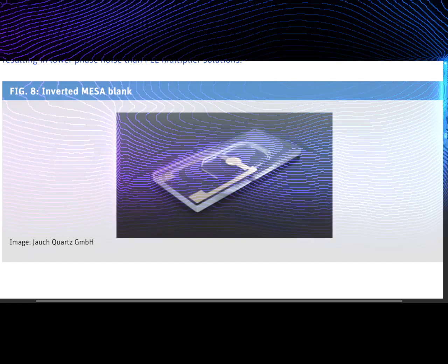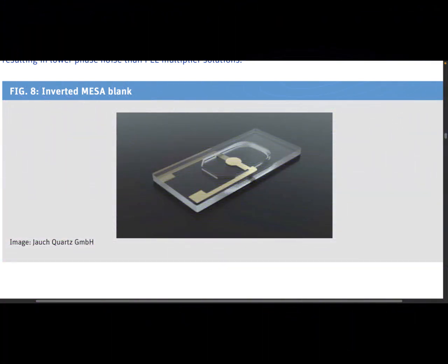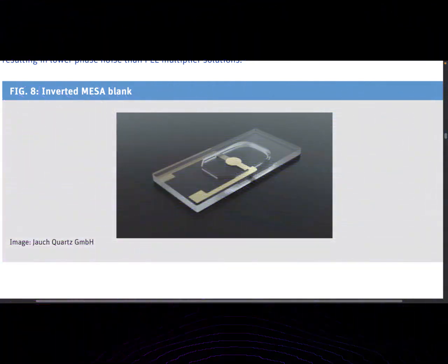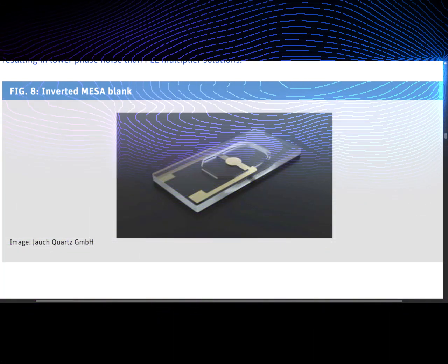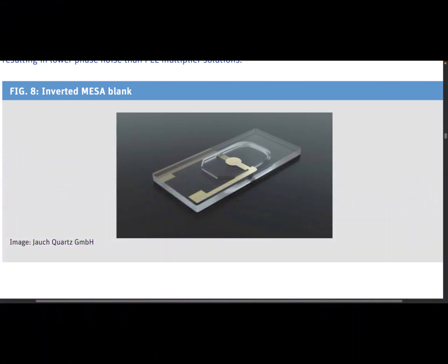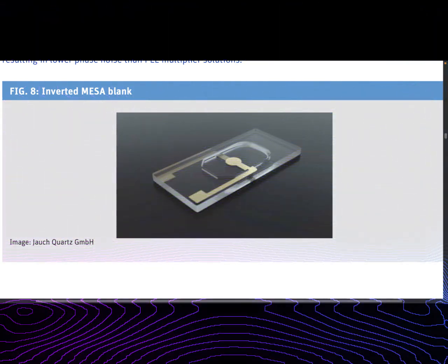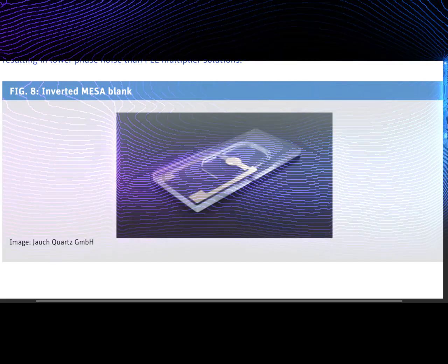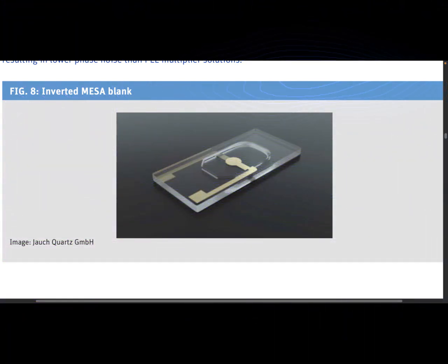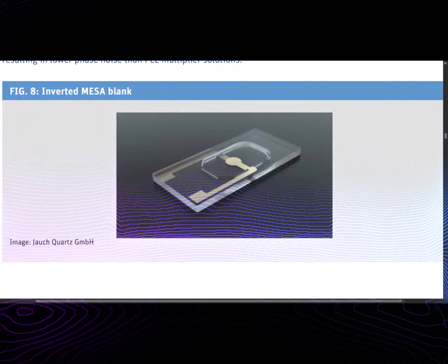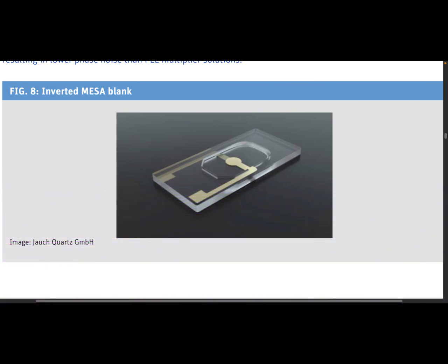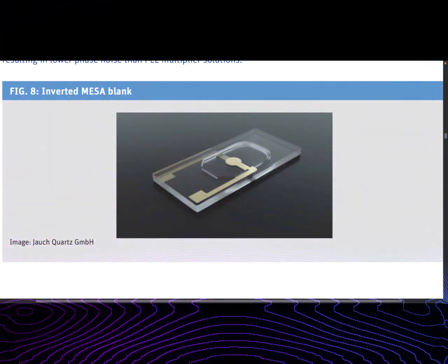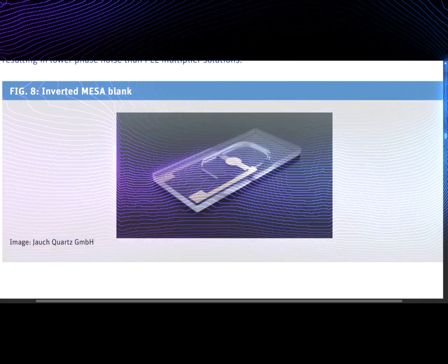Crystal resonators. To provide a more stable and accurate frequency reference, a crystal resonator can be used instead of an RC circuit. This uses the natural resonant frequency of a quartz crystal to control the frequency of oscillation. This is very stable due to its extremely high quality, or Q, factor. Crystals are also small and inexpensive for many common applications.